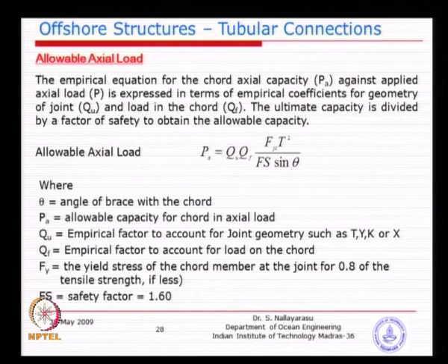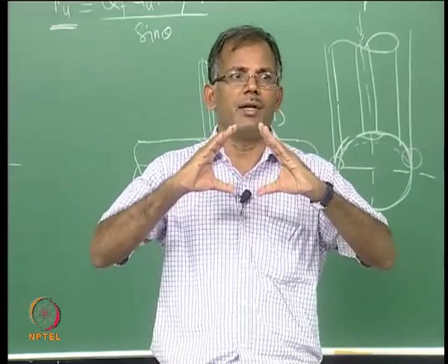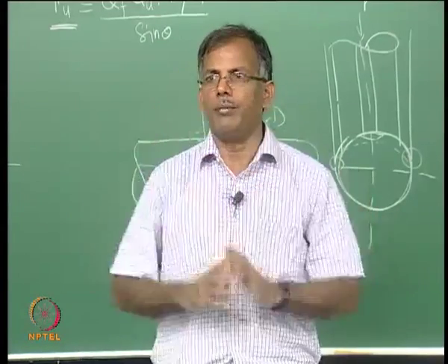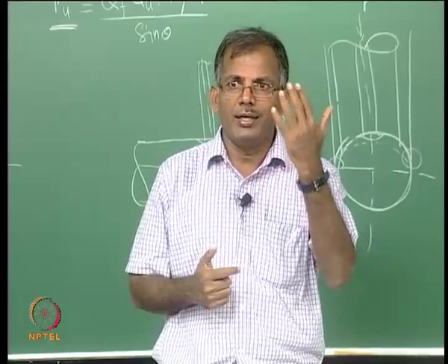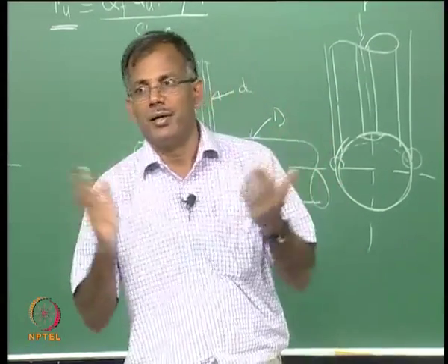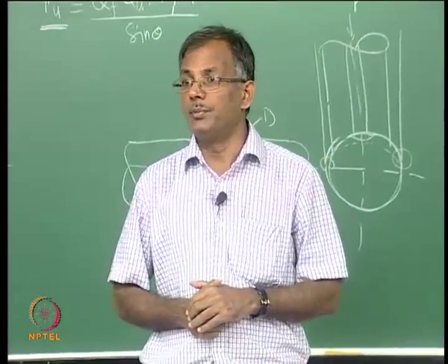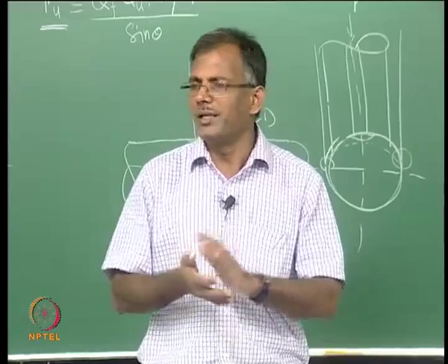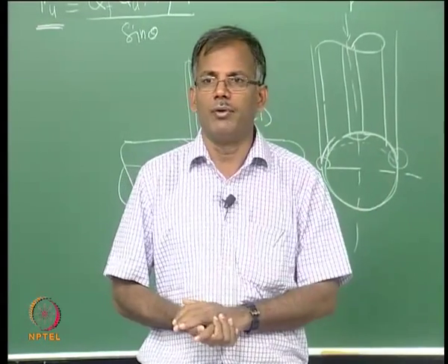So, now they have reduced to 1.6, utilizing the additional strength available in the tubular form, which I think you might have noticed we derived an elastic capacity versus elastoplastic capacity in bending and axial. So, you could see there is an increased strength because of the circular section. So, basically because of that finally the joint committee adopted a factor of safety of 1.6.